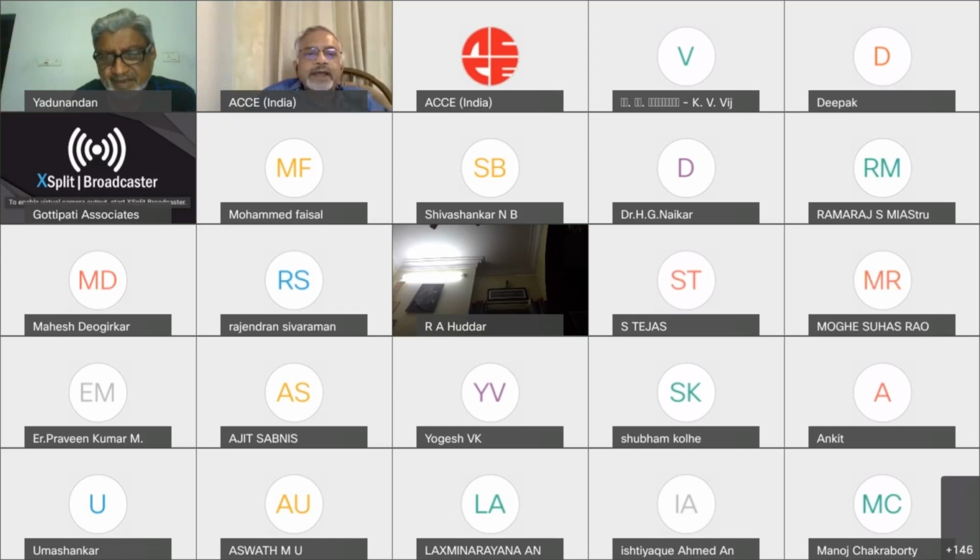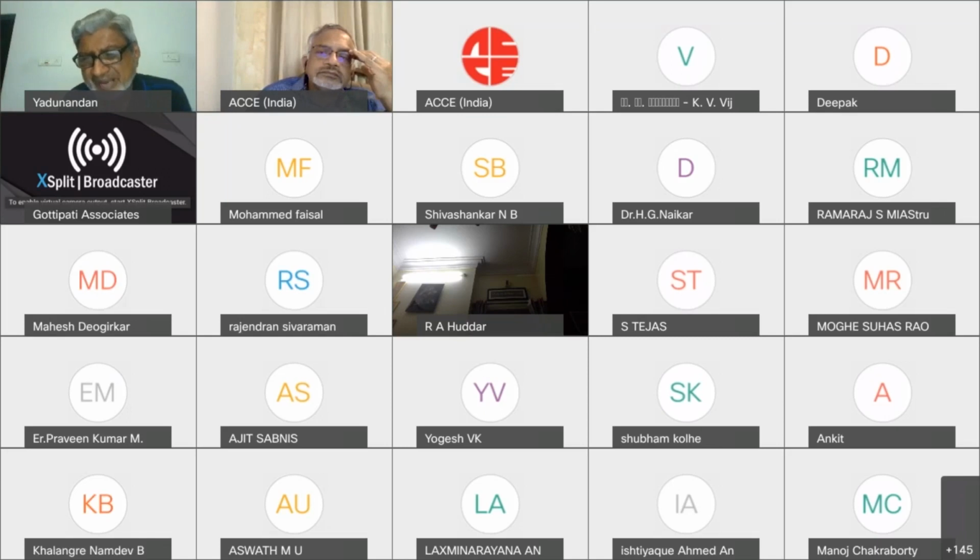Hello, Suhas Rao, please go ahead. Sir, when we consider base shear for earthquake loading, we will get high base shear at the bottom columns, right? Yeah. But while designing, we see columns of the same size from bottom to top. So what is your comment? Due to the base shear, the bottom column will have more shear, so we have to resist that. Yes. That's why we have to provide a little bigger dimension compared to the top columns. That depends. You can provide the same dimension, but the reinforcement will change.